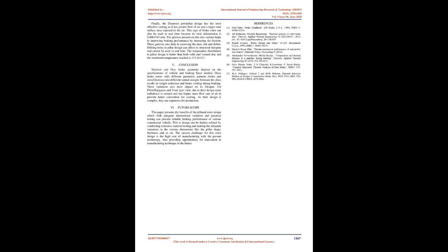This type of disc rotor can be used in real time as the deformation is very low, at 0.0003137 mm. When compared to the vane disc brake rotor, the solid disc brake shows better results in temperature distribution. The drilled holes in the solid disc brake reduce the weight and improve self-cleaning. This type is available at low cost compared to the curved vane brake disc.